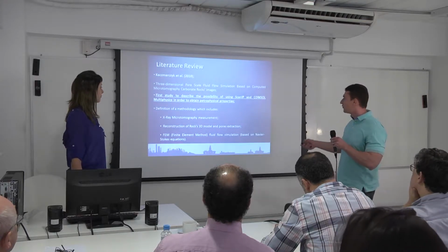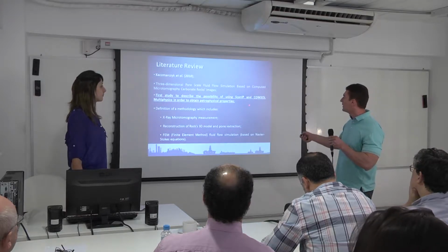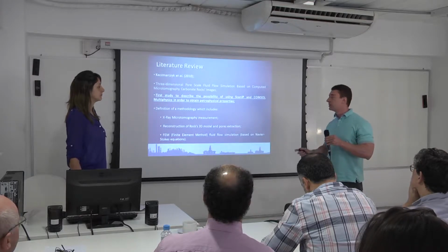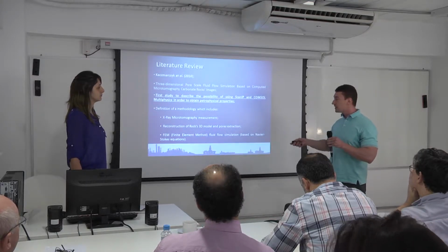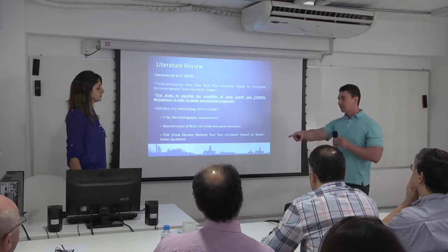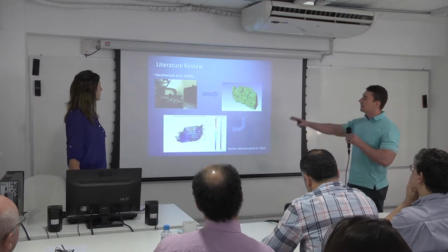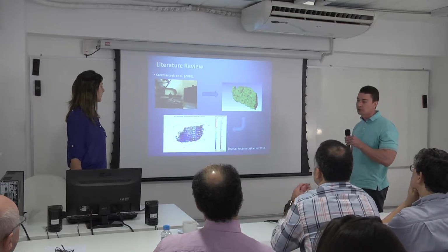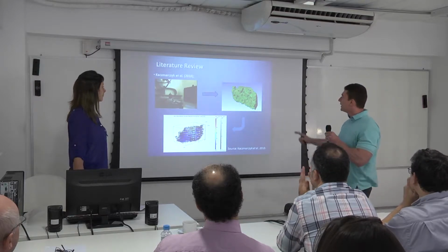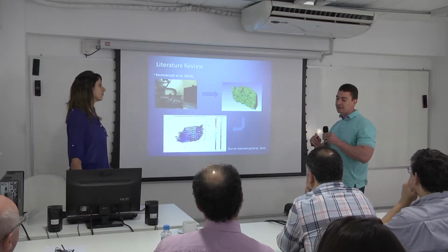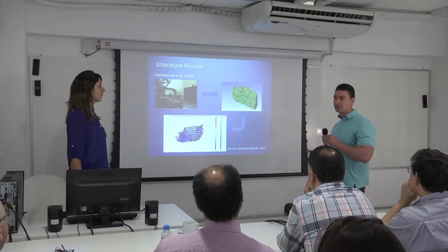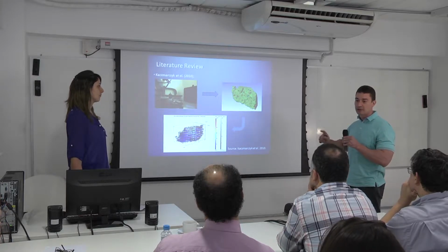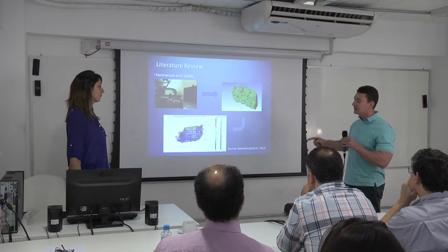This is the first study to describe the possibility of using ScanIP and Comsol. He also used the Avizo Fire software, which I will show on the next slide. In the first stage, he reconstructed the CT images, also using micro CT equipment. They reconstructed the first slice and created the 3D model through Avizo. Then they used the Simpleware software to reconstruct the interconnected pores, and exported the STL surface.